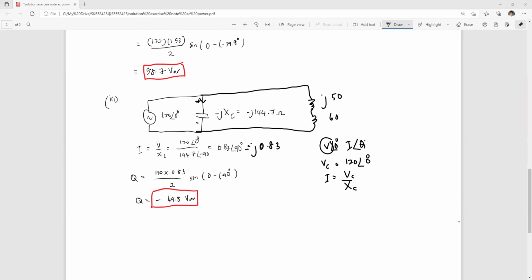An electrician suggests to you that the power factor can be corrected by connecting a capacitor in parallel with this load. If the capacitor size is just right, it will exactly offset the reactive power of the inductive load, resulting in zero total reactive power. Calculate the size of the necessary capacitor in farad, assuming that the line frequency is 50 hertz.